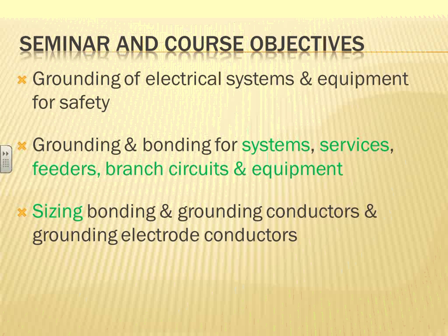I'm yet to see a building that's 480 only. Has anybody walked into a building that has a 480-only service, like a delta? Maybe center tap, 240/120 3-phase, but 480 only? Typically, guys, you need 480 strictly, and then they create a new neutral if they need to. Okay, what's the size?